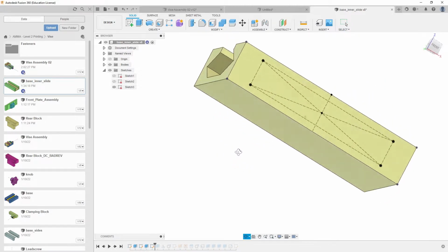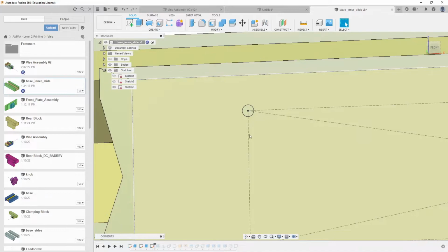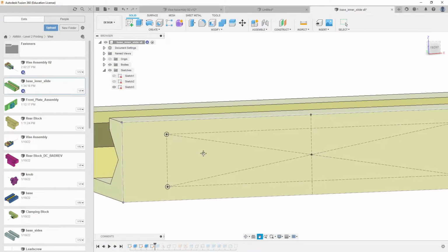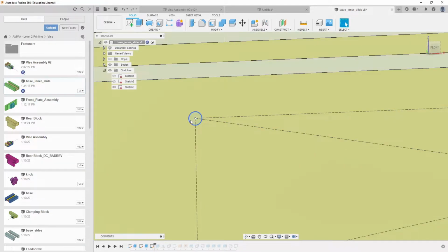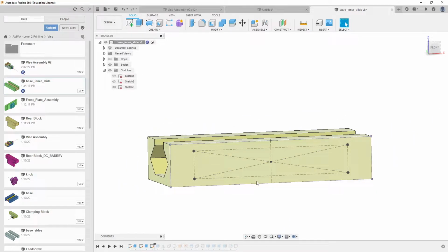So what's this sketch? Well, it looks like it's a square, but if you look closer, you can see that this is holes. I do this all the time when I'm making 4 holes for a bracket, a plate, a cover, whatever the deal might be. So you'd make a construction square first, that's the dashed lines, and then you make a solid circle. The solid circles can be extruded, the dashed lines cannot, so that's why the dash is considered construction. It helps us build the thing.